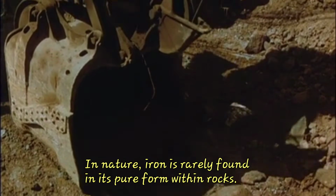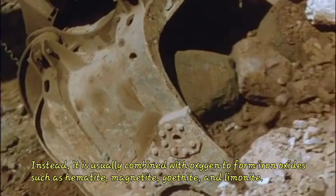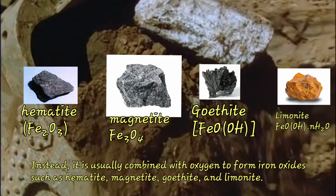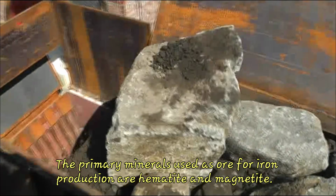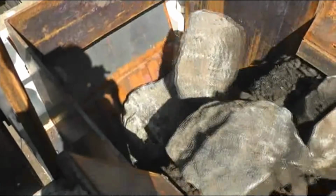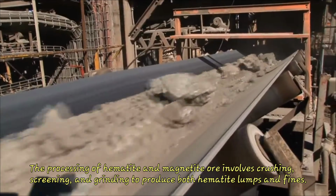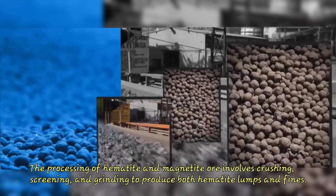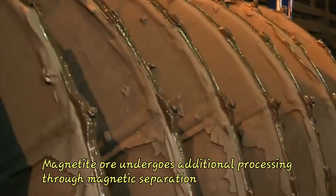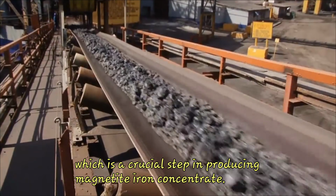In nature, iron is rarely found in its pure form within rocks. Instead, it is usually combined with oxygen to form iron oxides such as hematite, magnetite, goethite, and limonite. Primary minerals used as ore for iron production are hematite and magnetite. The processing of hematite and magnetite ore involves crushing, screening, and grinding to produce both hematite lumps and fines. Magnetite ore undergoes additional processing through magnetic separation, which is a crucial step in producing magnetite iron concentrate.